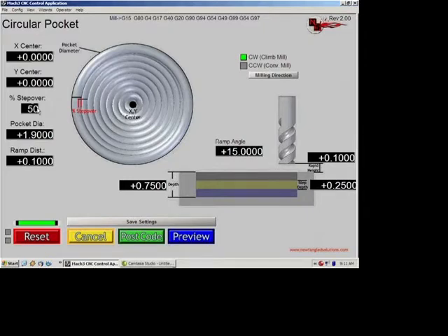That's a little bit, maybe not as important on the spiral fluted, but if you're running carbide inserts and stuff, that can be actually detrimental to the life of the insert. So if you're running carbide tooling and you find you're having some bad life, try and bump that down just a little bit, and you may actually get better life for your tool. We're going to bring this up to 75 for our first example.